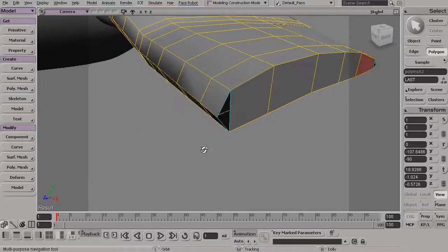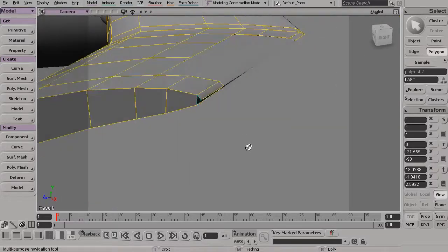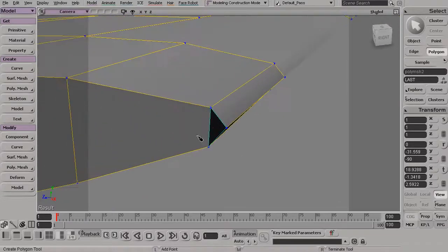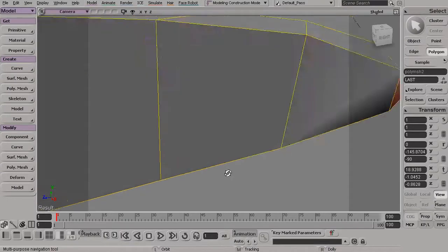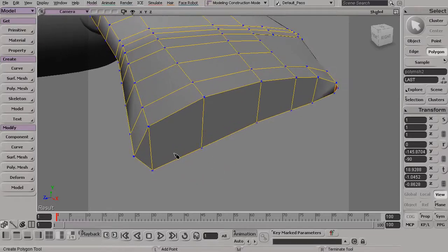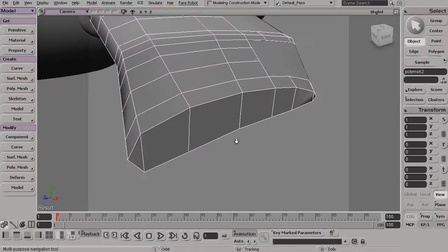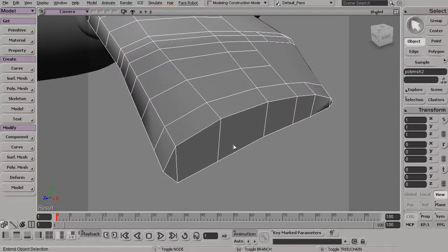And you can start to see very quickly how we can begin filling these in. Now over here we have these little empty edges as well. So again, just left click, come over here to a joining edge, left click, and then right click when you're done. Looks like we have one more down here, so again, left click, connect it up, and then right click when you're done. Now to just simply get out of this tool altogether, once we're finished connecting all these together, just simply tap your space bar, and now we're back into a normal object mode.